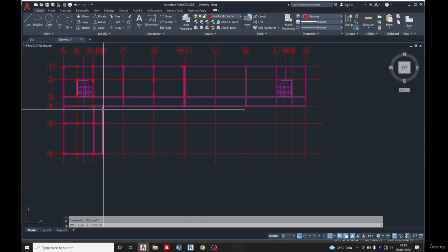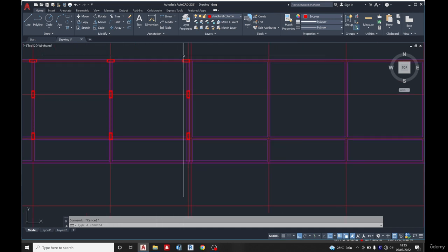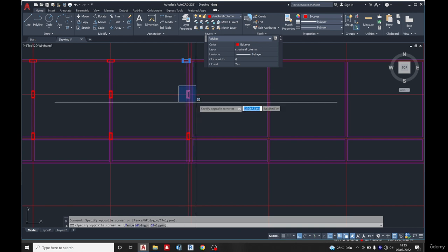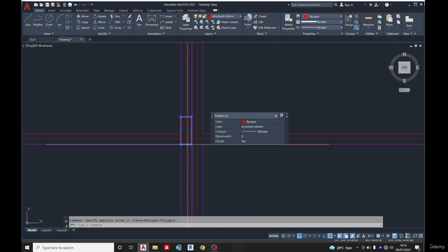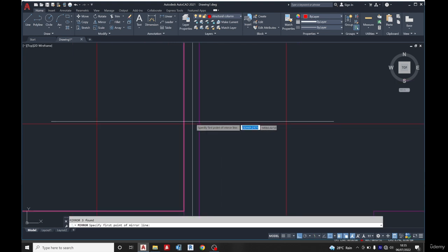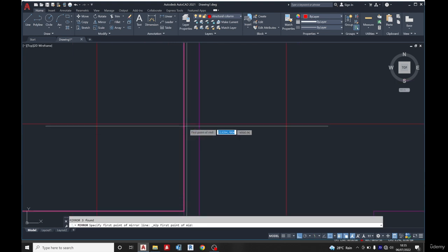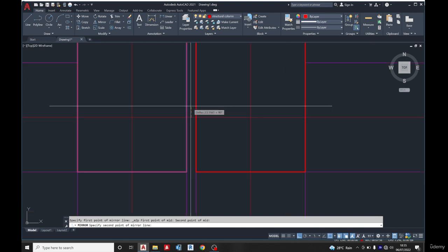I'm done with that. So I'm not placing any column at the supports here, which I can decide to design as a cantilever even without the beams, but I'll use the beams there as stiffeners. What I'm going to do now is select these columns. Okay, select this, select this, select this, and I'm going to mirror. So you can see I have a mirror plate, but I've not created a mirror line. So what I can do is pick the center between here and here, then mirror it.